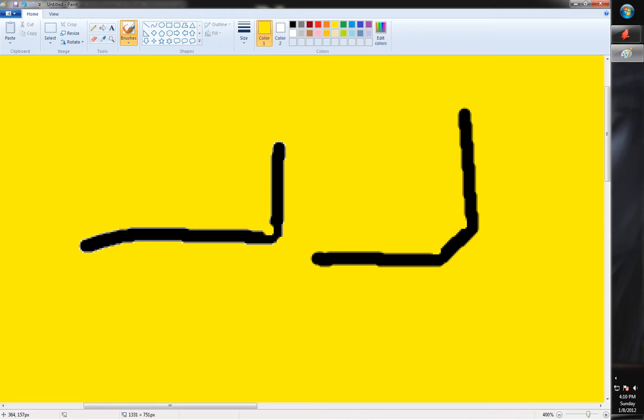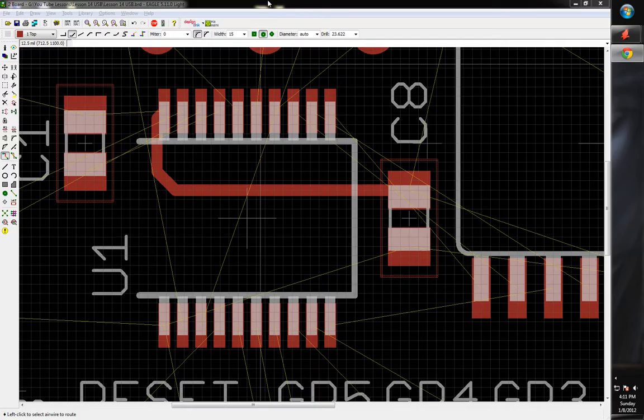Angles will always give you a little bit higher resistance, but still, one of the main reasons is just the etching process and things that are called acid traps. So you don't want any acute angles. You want all obtuse angles. You don't want anything like this going on, because if it happens, it's going to chew out quite a bit of your trace when it does its thing. So no acute angles, all obtuse angles. Anything has got to be greater than 90 degrees, otherwise you have, or could possibly have, etching issues. So that's that brief little piece.